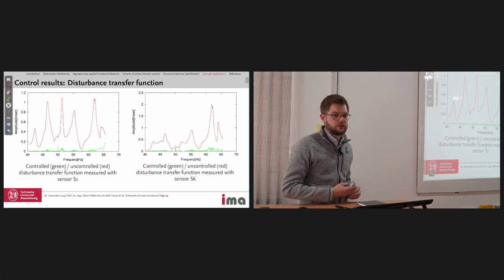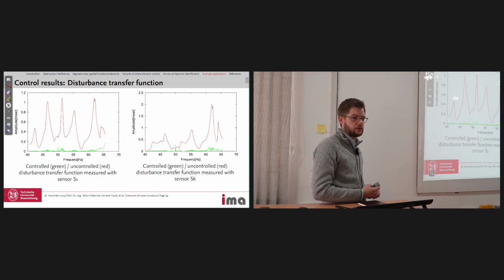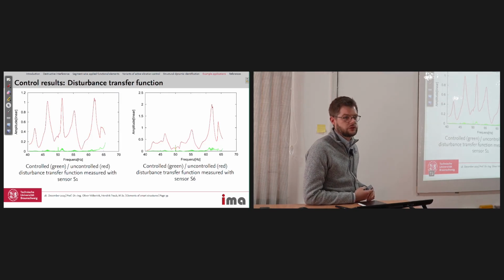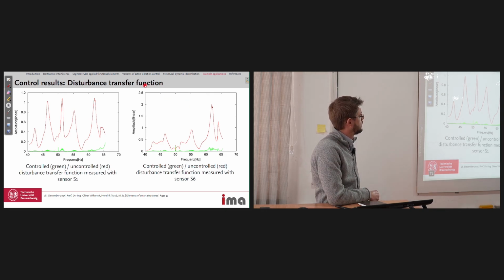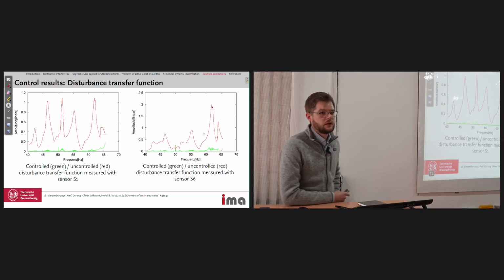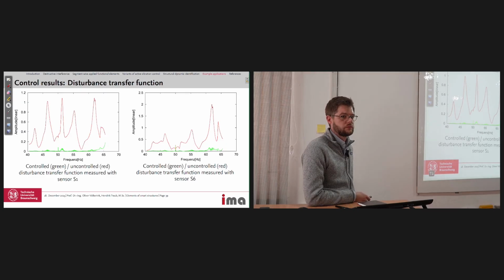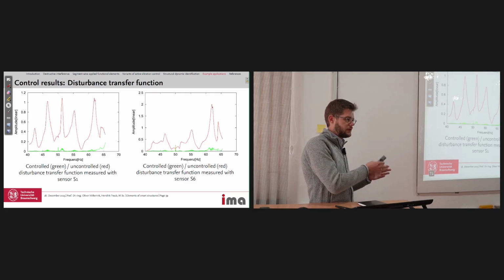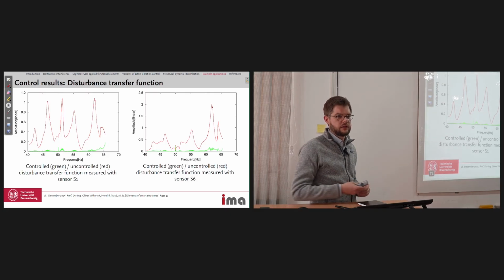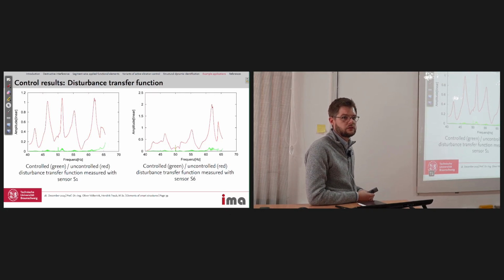If you have a model of your structure where you want to suppress the vibrations, from the modal analysis you know the eigenfrequencies as well as the amplitudes, and then you can select the eigenmodes you want to suppress. So I think it depends, as always, how close the model is to the real structure, but at least if you have a model initially, then that should be possible.